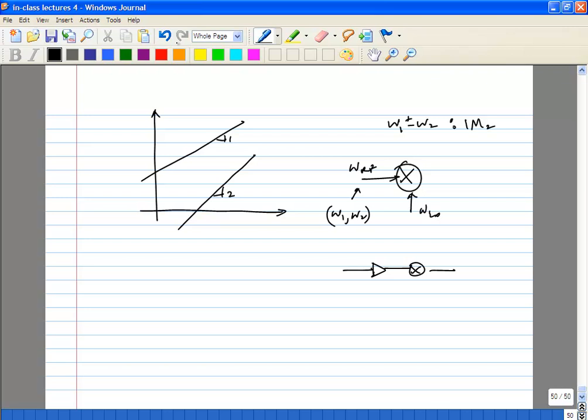There is a transconductance followed by the real mixing, which is the switches. So this one is the one which has nonlinearity. This one we don't care, it is just a switch. We modeled it as the signum function, right? So most of the nonlinearity actually comes from the transconductance. Okay, so if you put in 2 tones, at the output here you are going to get omega 1 plus or minus omega 2 and that will get mixed down.